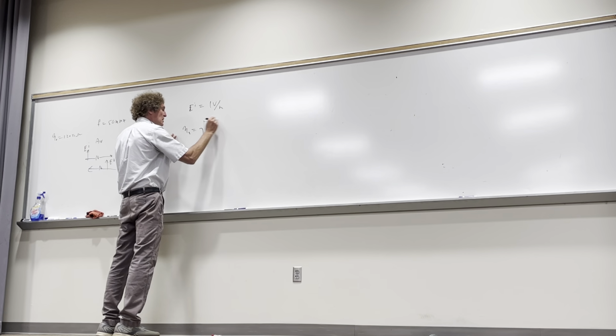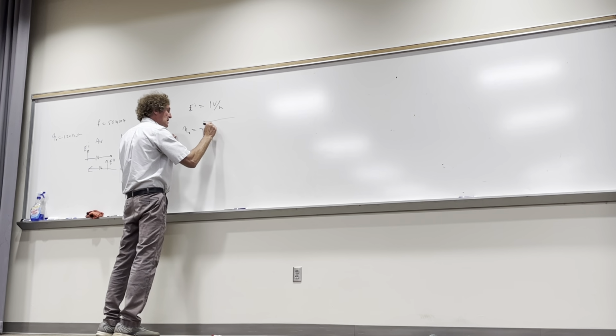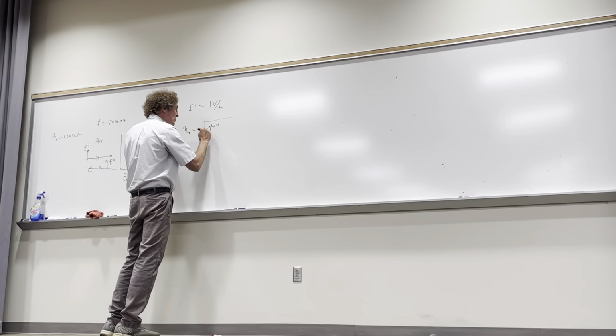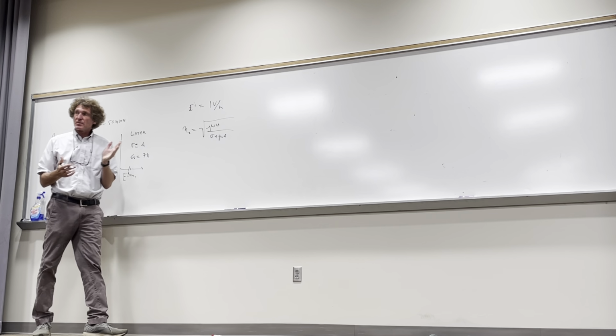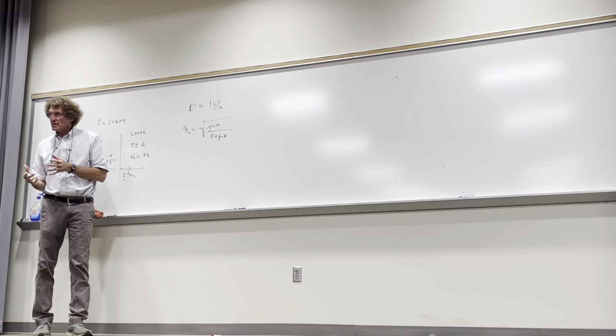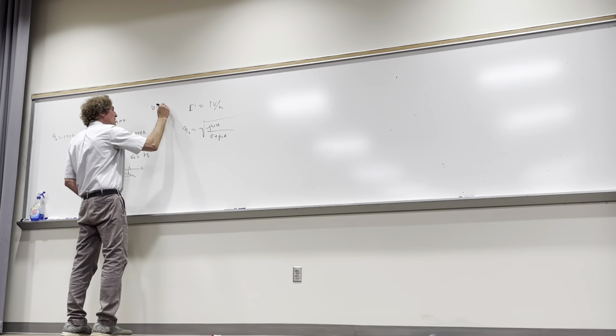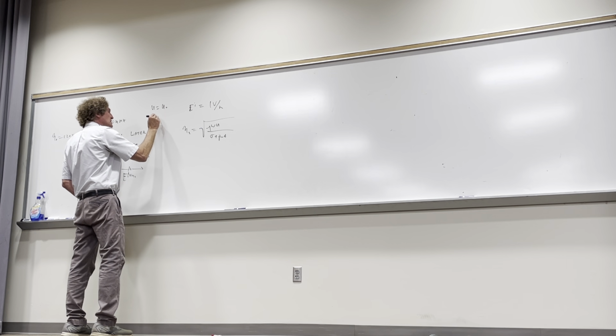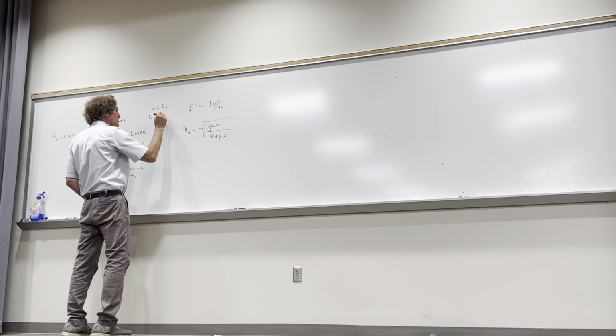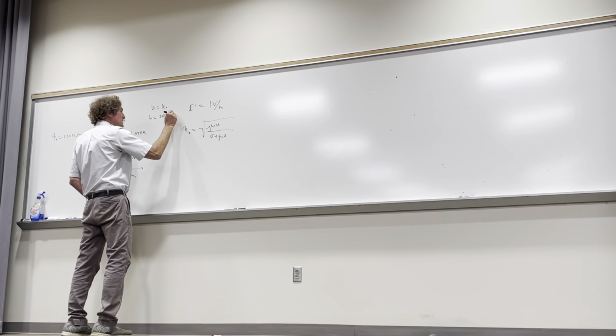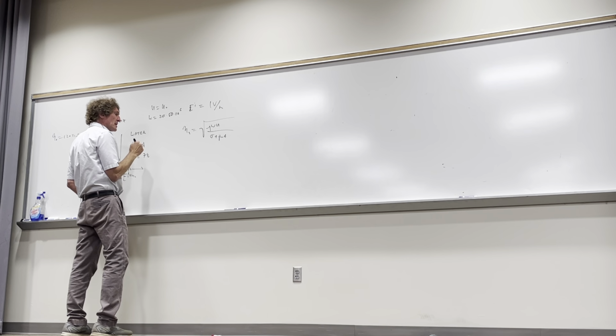And that's going to be the square root of j omega mu over sigma plus j omega epsilon. Now that's the general form, and I'm doing it that way for a reason. You all agree with this, class? All right, here for ocean water, mu is just mu naught. Omega is 2 pi times 50 times 10 to the 6.